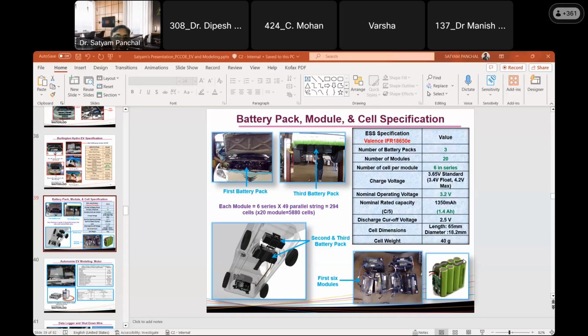Maintenance wise, while running the vehicle, we already have some technology to monitor the battery. Other than that, as an owner of the vehicle, what things does he have to take care of on the battery physically? So BMS, cell to cell variation. Let's say if you have 300 bigger cells, or 6,000 cylindrical cells, you have to have a good BMS system in order to get correct voltage from all batteries. Let's say out of 6,000 cylindrical cells, 200 cells are not working in one of the modules, then how will you know that? Those types of hurdles are big issues right now. So cell to cell variation, meaning voltage variation, is one of the big parts when it comes to this question.